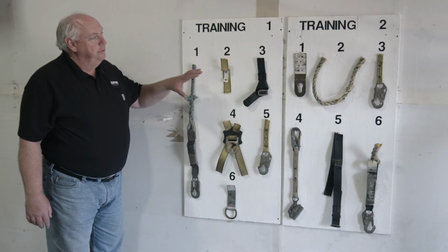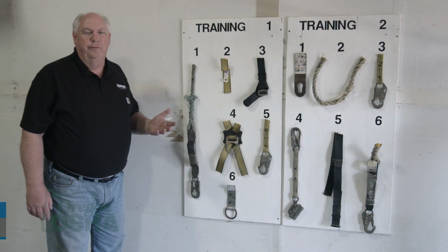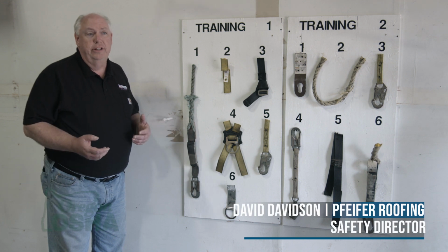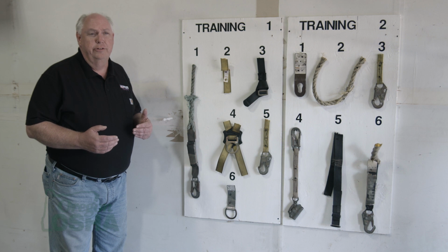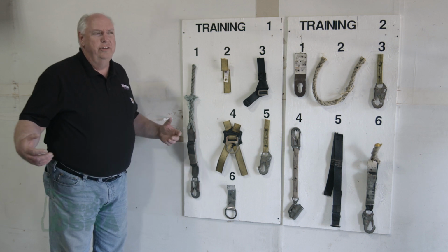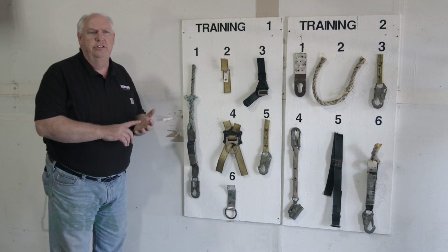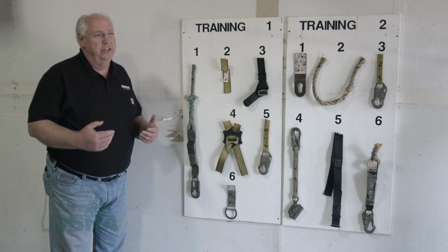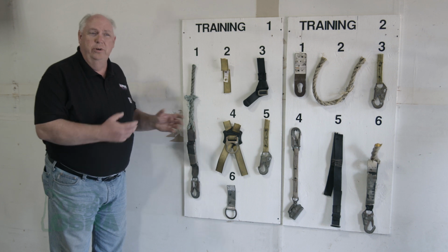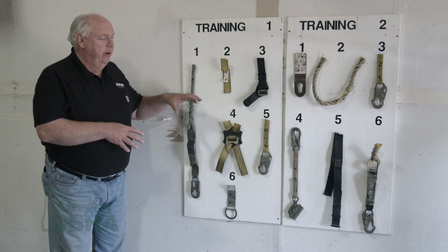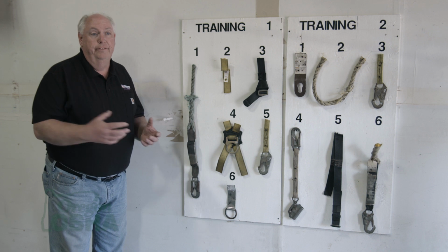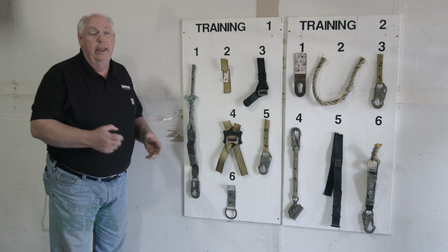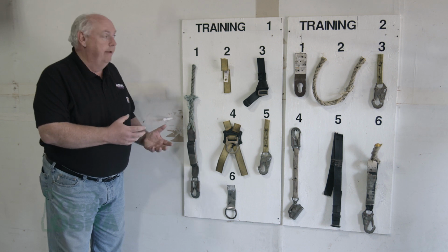So these are a couple of training boards that we have. We do these for new hire orientation, as well as we'll bring them out during safety meetings and run the guys through some safety reminders on their fall protection gear. So harnesses, ropes, those types of things, making sure that they understand what they're looking for when they're doing their inspections, with real world examples. I grabbed all of these props off of equipment that was no good and that I confiscated, and then used them for training. So that's what we have here.